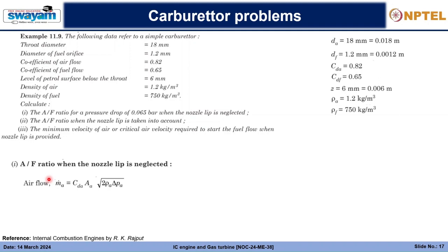Note that we are not given the temperature at the inlet conditions. When the temperature at the inlet conditions is not provided, we need not follow the exact analysis, which has a bigger formula that is quite monotonous. Instead, we can follow the easier approach, that is the approximate method.